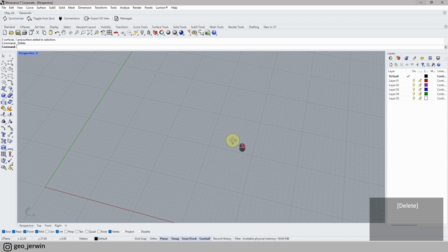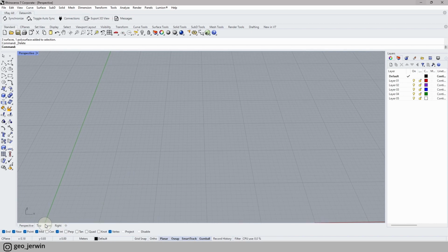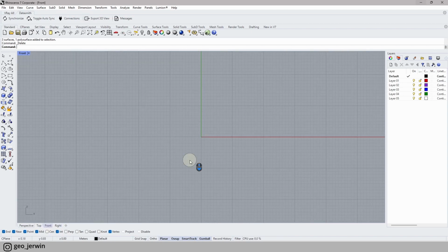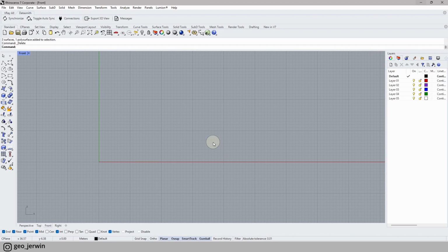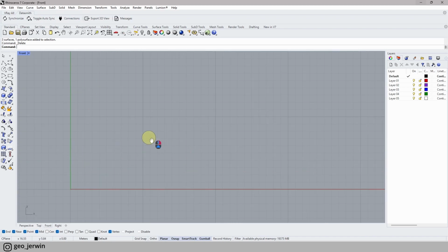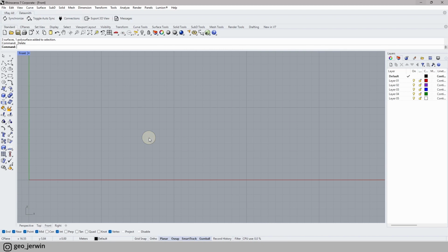And let's go through an exercise, right? So let's do an exercise with Rhino, and then we can see how to connect it with Grasshopper. Cool. So first, I'm going to go to top view or maybe front view. And let's create a tunnel, a parametric tunnel. We'll add some Grasshopper stuff into it and let's make it parametric. Why not? So it could be like a twisted tunnel, right?